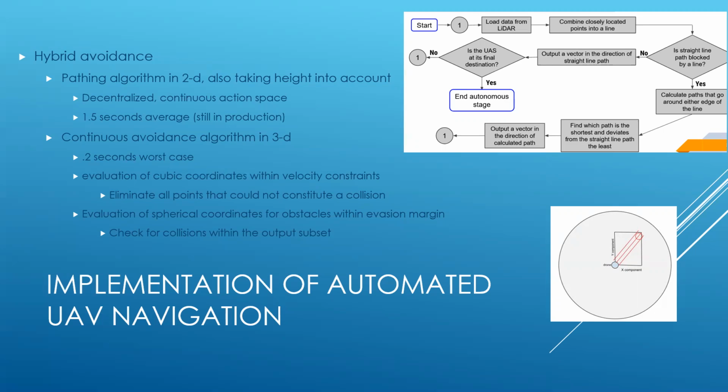From the subset of data points, if any, the angles of these points are judged by comparison to the angles of the velocity. If any matches or near matches occur, the algorithm will report a collision and avoid the obstacle, and the pathing algorithm will be repeated to find a new valid path towards the target.